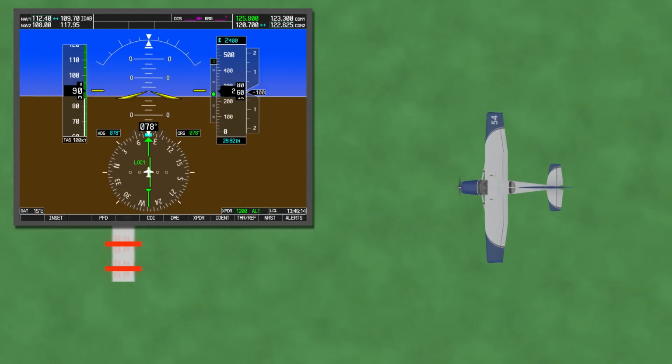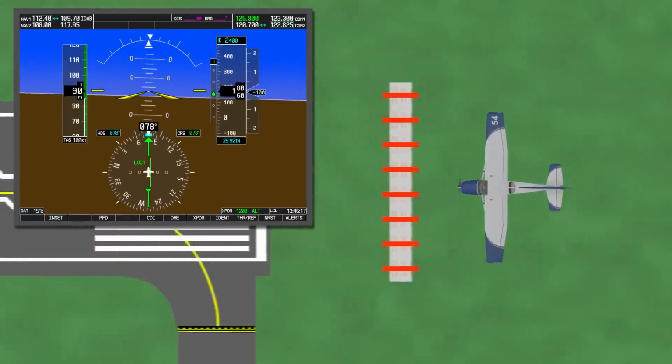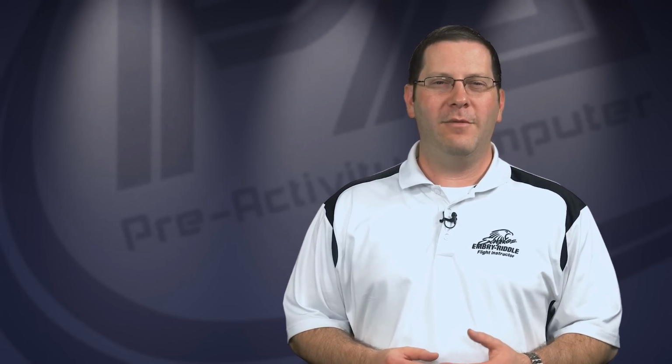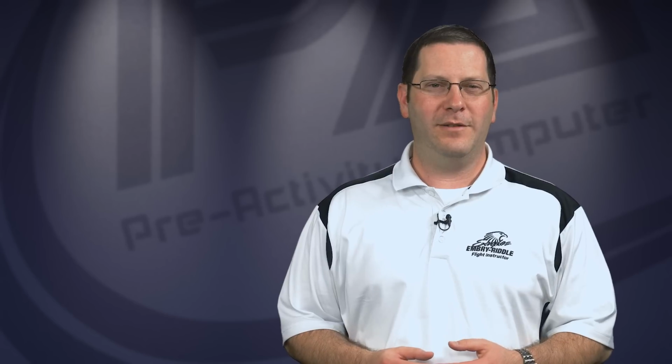Be aware that as you continue to track the back course, you will lose signal as you cross over the antenna, much like a VOR. An ILS approach is a precision approach that provides both vertical and lateral guidance to the runway. With typical minimum and visibility requirements that allow a landing with 200-foot ceilings and a half-mile visibility, the ILS approach will remain a favorite approach of pilots in poor weather conditions.